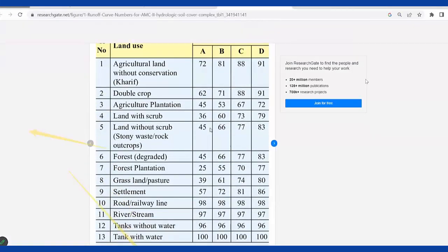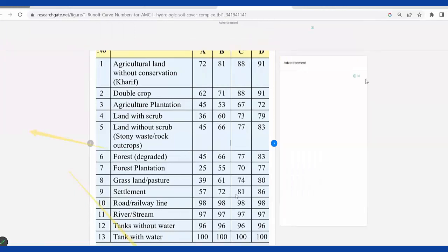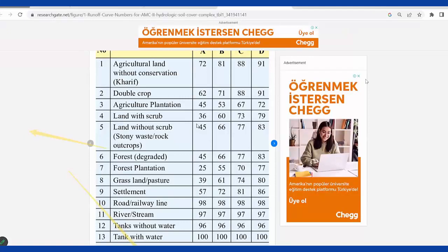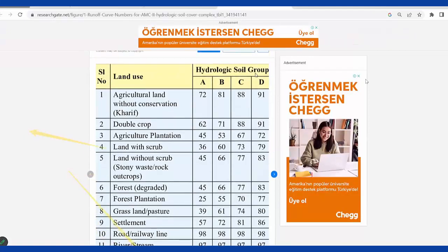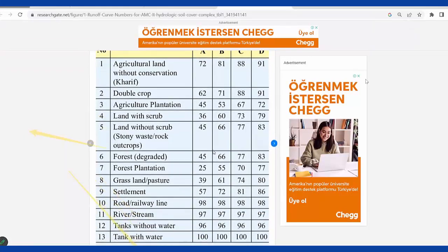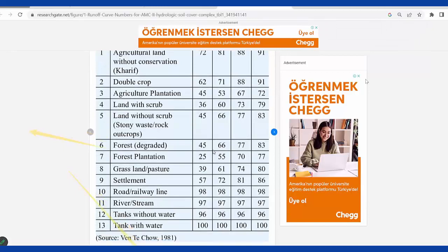The soil type, if you remember, I defined something like 82, and the one that we are using, hydrologic soil group, is that one, but we are using that soil type for Snyder and Mokus methods.